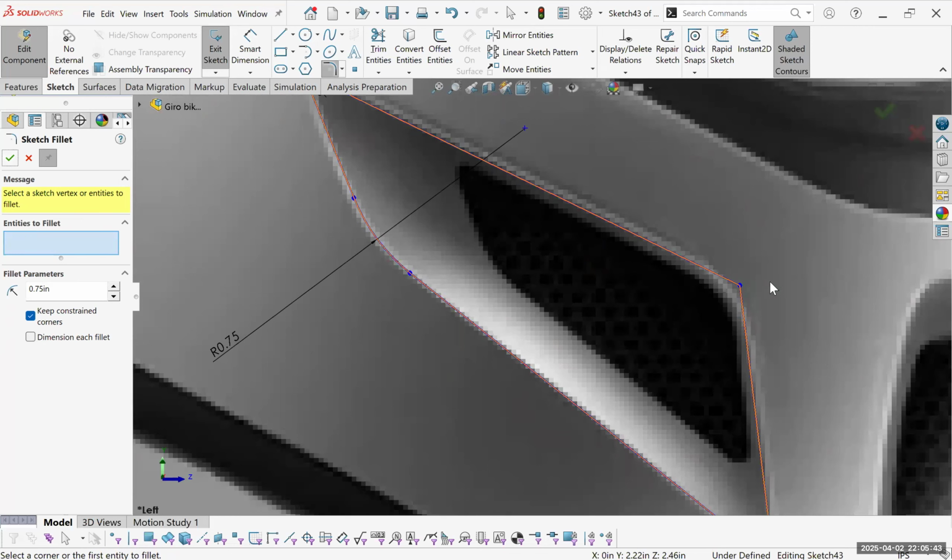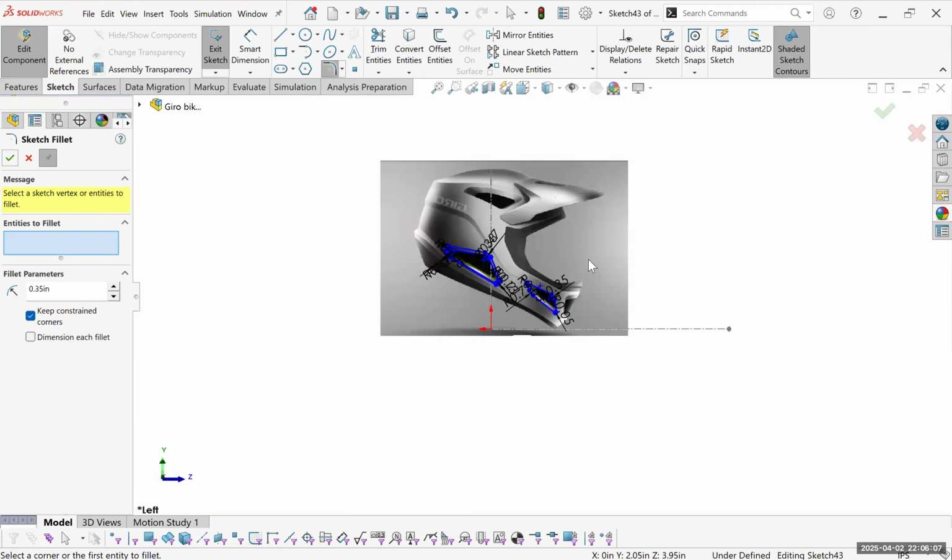And we'll do the same thing on the inside. The reason I'm doing it this way is because I want to have flat, curve, flat. So maybe loft to the inside. They have a similar number of edges or sections. If it doesn't loft, then in that sense, I could actually go ahead and do boundary surfaces from fillets to fillets. All right, so this is also done.